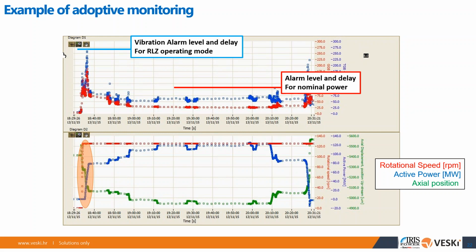A few more questions. Have you looked into evaluating similar rough zone operating areas on blade type turbines? You mean on the Kaplan turbines? I'm not sure if that's a question, but Kaplan turbines do not have it. I mean, we have seen similar effects also in Kaplan bulb turbines, actually, but because they have adjusted pitch of the blade, they usually don't have these problems.